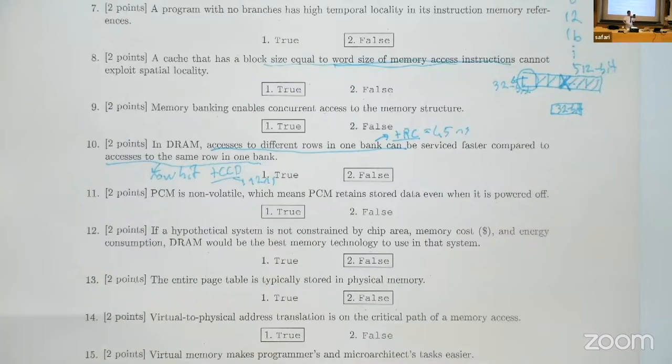Not exactly like that. It's just that when you have a row already enabled and you want to access another row, you have to first pre-charge the bank, like close the open row, and then activate the next row, like the actual row you want to access. And you have to wait a very long time to do those operations. But if you're accessing a row that you have enabled, that means you're servicing that access from the row buffer. So it's already enabled. You have the data ready to be pushed through the I/O, essentially, out of DRAM. That's why it's much faster.